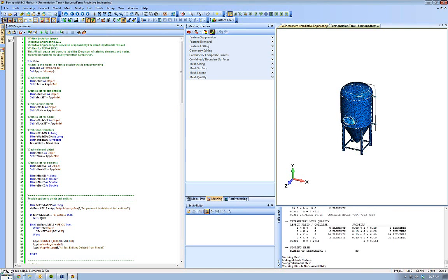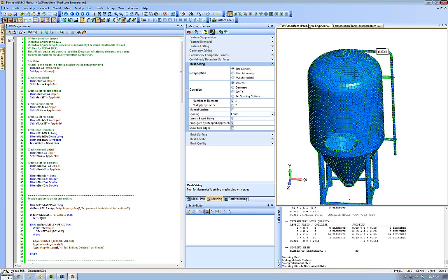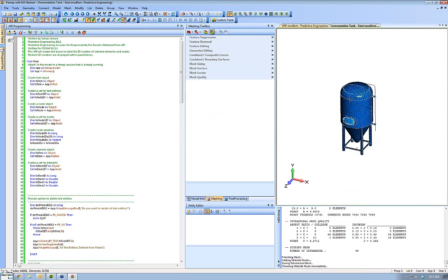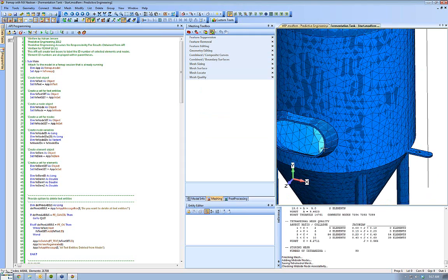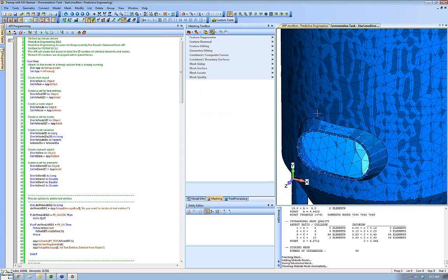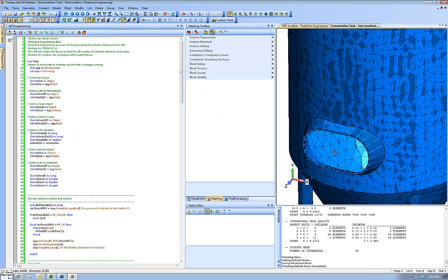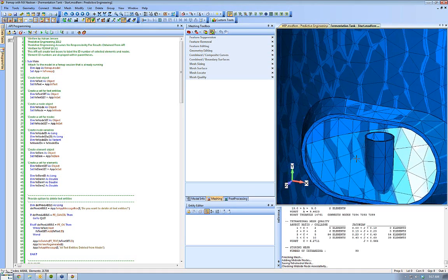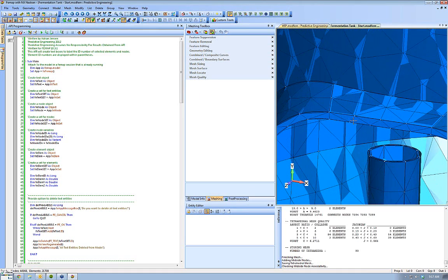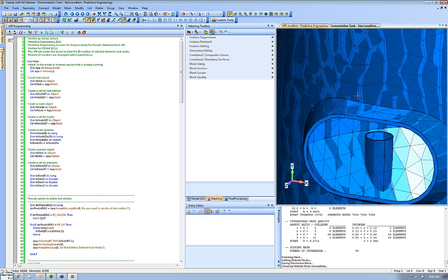All right, so we are sitting at 44,000 nodes. That's almost a 10x increase for a similar mesh size. If you think about that, we haven't done any work to increase the mesh quality or the mesh density around our problem areas. And if we look at the thickness here, we only have one element through the thickness of this plate. And we're going to have a hard time capturing the bending effects, kind of the through thickness stresses, just because we're not going to have the same sort of resolution as we would with plates.